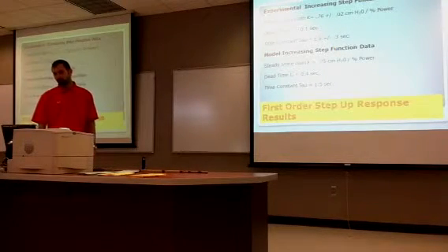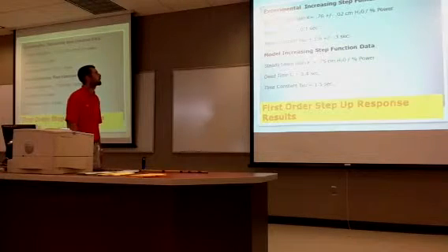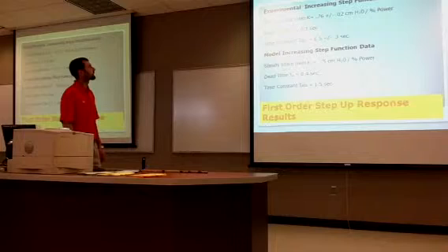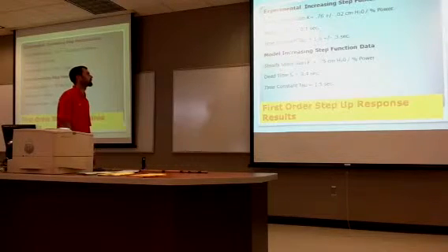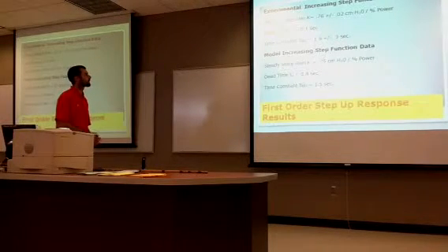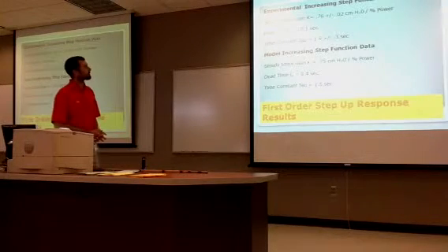The experimental increasing step function data ended up with a steady state gain of 0.76 plus or minus 0.02 centimeters of H2O. Our dead time, whether going up or down, always ended up being 0.1 seconds. And our tau was 1.5 plus or minus 0.3 seconds.